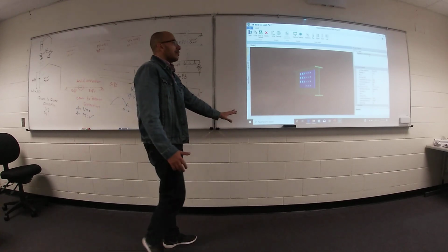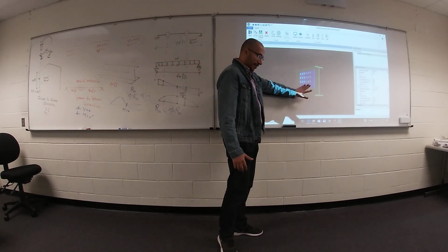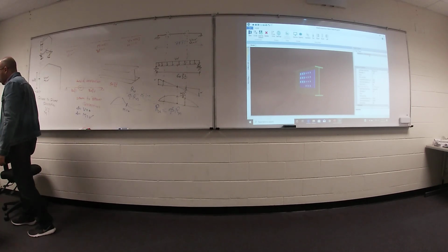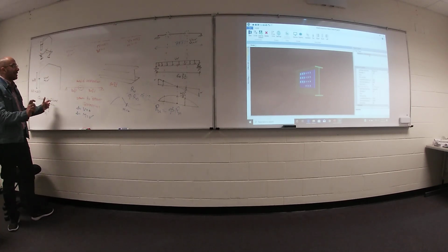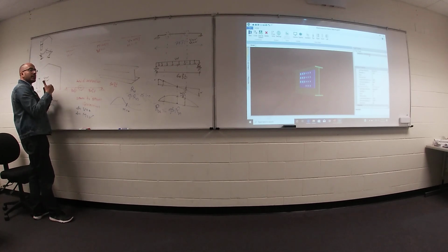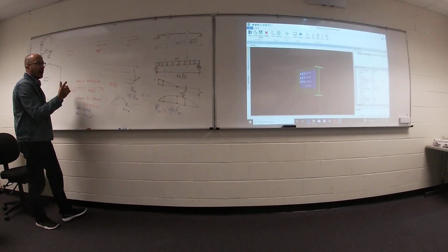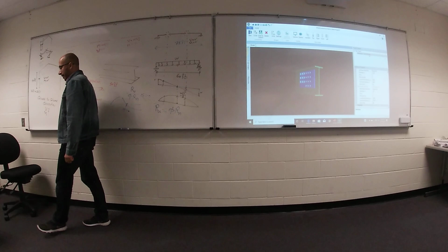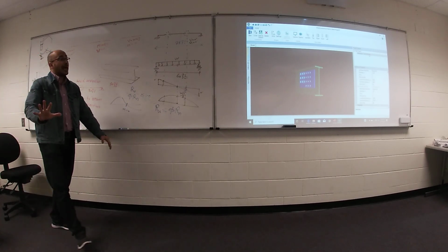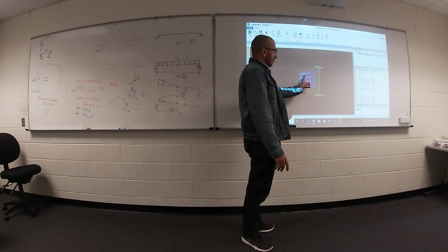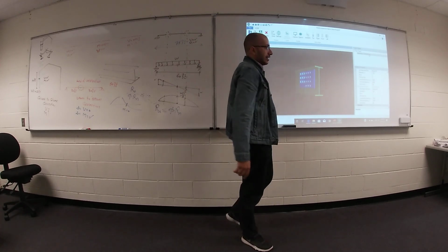This is the first type of connection, called a shear connection, beam to beam shear connection. We have a limited length of beams, so sometimes we need to make a splice, a connection between two beams, to construct your total beam length. What will happen if this beam supports shear and moment? What do you think?